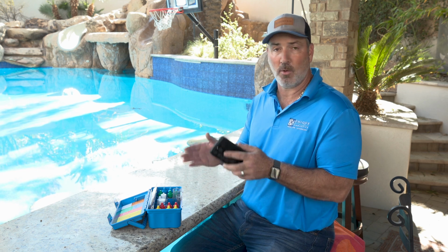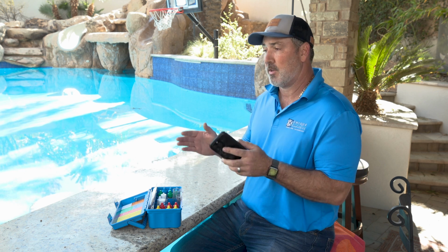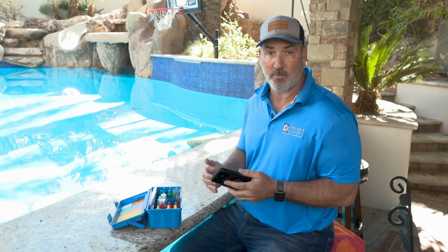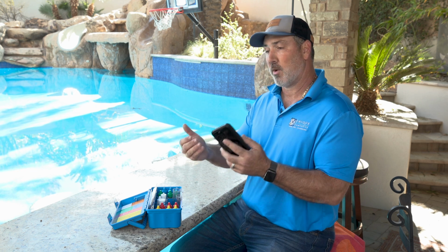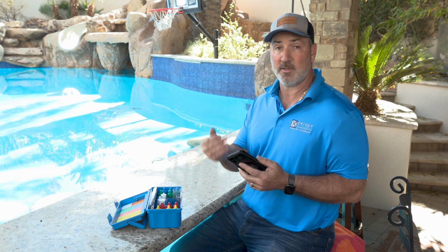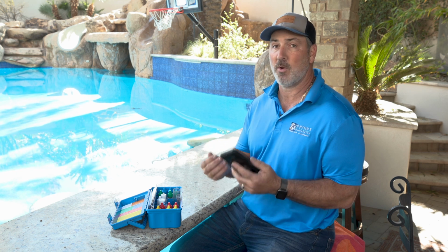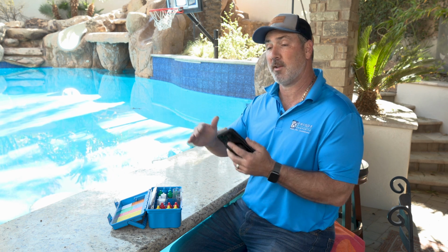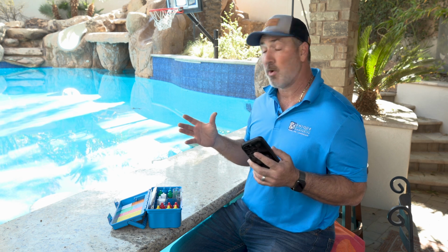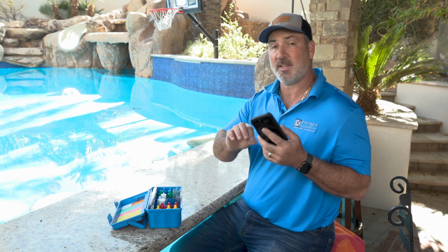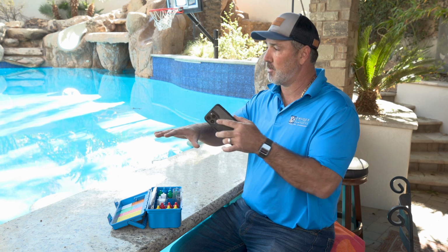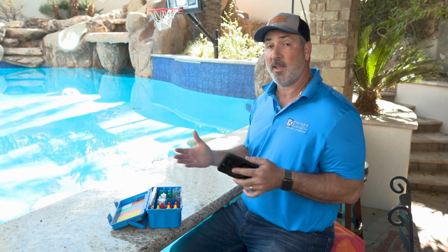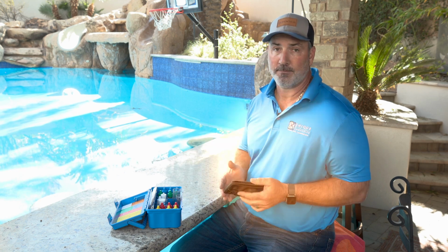So you can't just test chlorine and pH and call it a day, because you can still have damaging effects and aggressive water. Aggressive water is water that might be very low on the LSI to where it's wanting to pull more calcium out of the interior finish. It starts to etch your pool. It starts to eat away at your pebble or your plaster. And quite the opposite, if you have a high LSI, you start to get scaling. So calcium is going to want to attach to the water line and to the pool. You can have things as bad as mineral precipitation where you have calcium and scale that builds up on the surface of the pool. And all that can happen with a poor LSI.